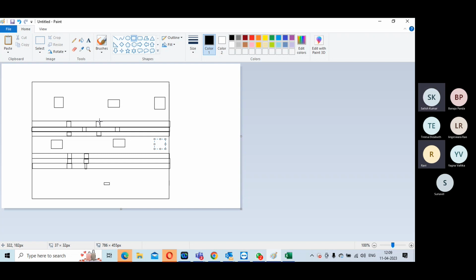It will impact in a certain way because you are actually trying to block this area for space. But that is the requirement, right? Most of the issues will come in the most complex areas. Wherever your critical path is, critical path means where the timing is very critical, in those paths mostly you will have a lot of bugs or timing issues. When the timing path is very critical, that means the cells are going to sit very close. The density is going to be close to 100% in that area. So that is an exclusive bound, right?